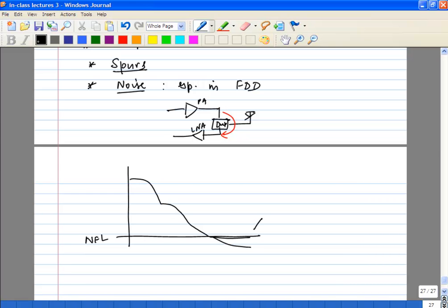But what is this noise floor defined by? It's defined by the circuits of the transmitter. And this is your TX center frequency, and eventually there is going to be a point where you have an RX center frequency. So the noise of the TX at the RX frequencies in the RX band is going to leak through the duplexer into the LNA input and effectively increase the noise floor. Is that clear to everyone?